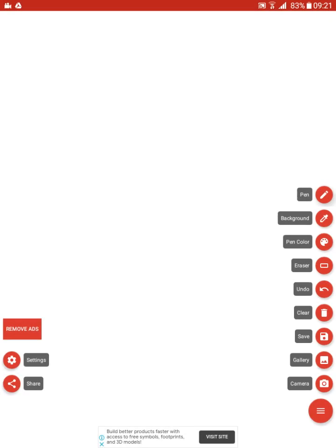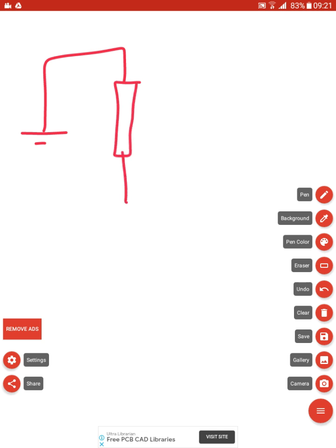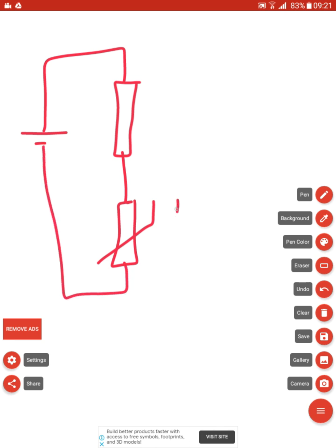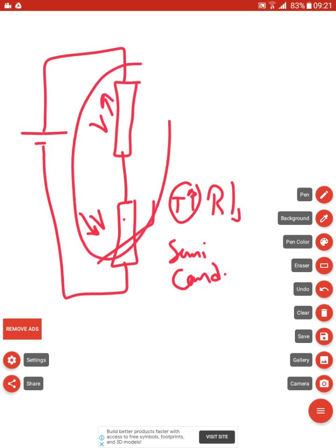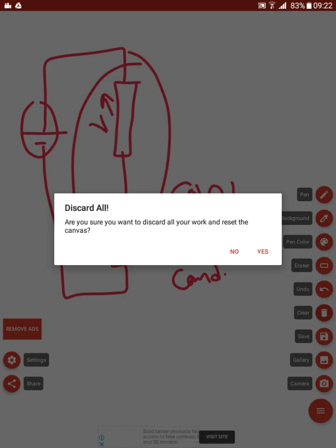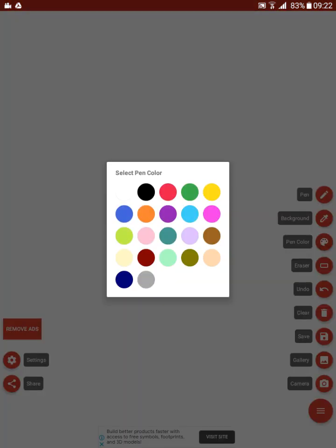Another way to split the voltage is using a thermistor. We have a constant resistance and a thermistor like this. If the temperature of the thermistor increases, its resistance decreases because it is made of semiconductor, okay? So increasing the temperature, this resistance will decrease. So the reading of this voltage here will be less than the voltage here, but the total of these V1 and V2 has to be equal to the electromotive force.